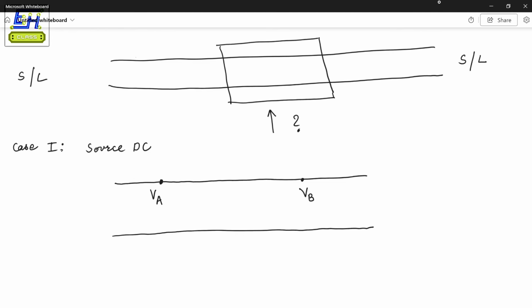If this is a DC line, we know that voltage closer to the source will always be higher, and that decreases with increasing distance towards the load, because load actually consumes it. So the electrical pressure, voltage as we say, actually decreases, right? And added to the fact that resistance and losses of the line itself decrease the voltage further.